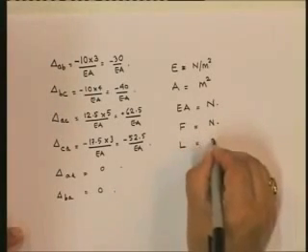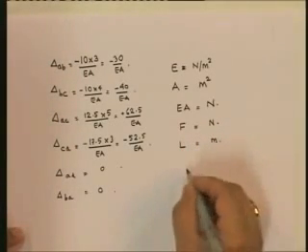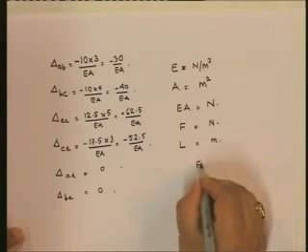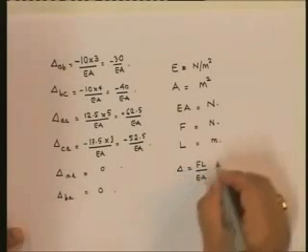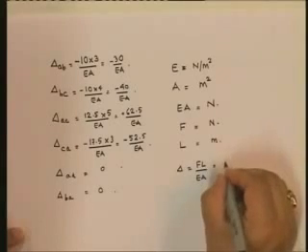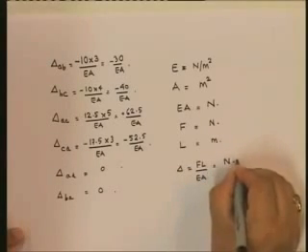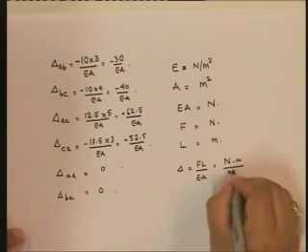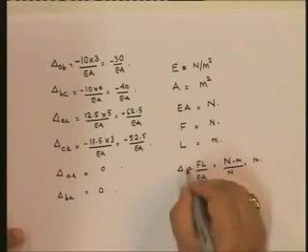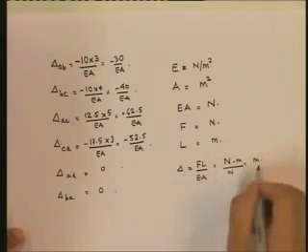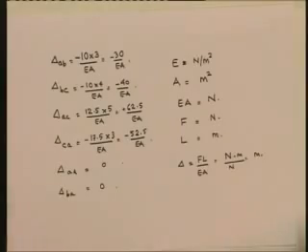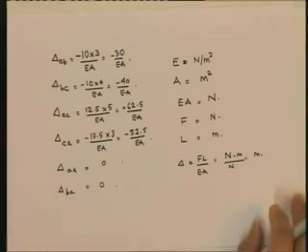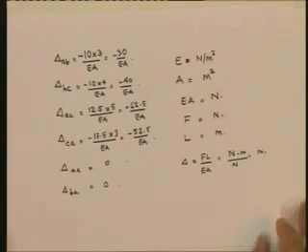And length is in meters. So now when I write delta is equal to FL upon EA, let's see what I'm doing actually: Newton meter upon Newton meter. Units are consistent. Delta, which is the displacement or deformation, has to be in meters. So we have dimensional consistency, and that is very important to know when you actually solve a problem.